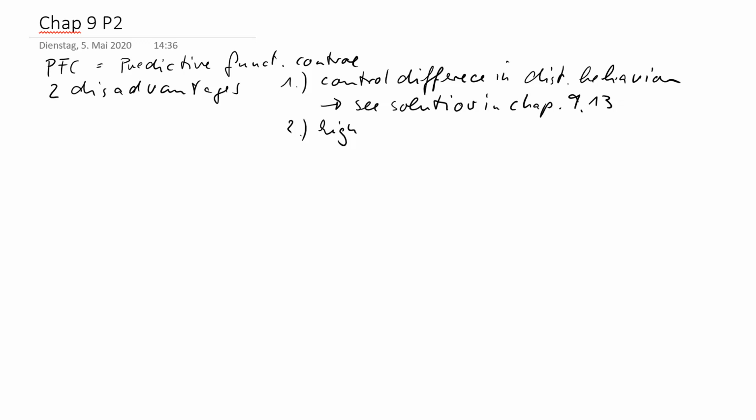High noise gain if T0 is small. So what we can say is the controller will be very fast depending on the sampling time. The smaller the sampling time, the faster the controller, but the larger is the noise gain. To show you this, note: